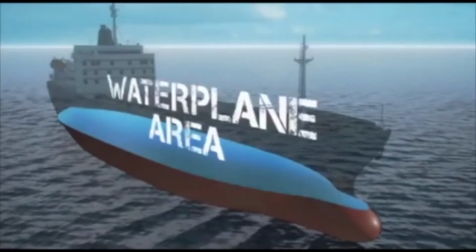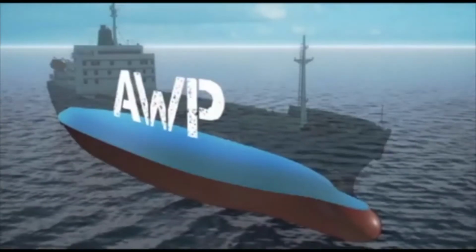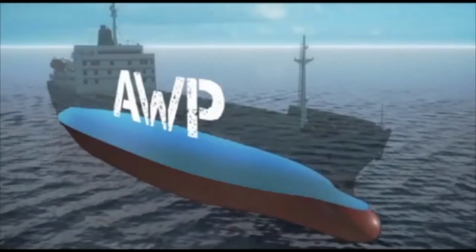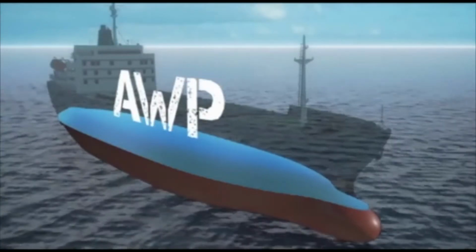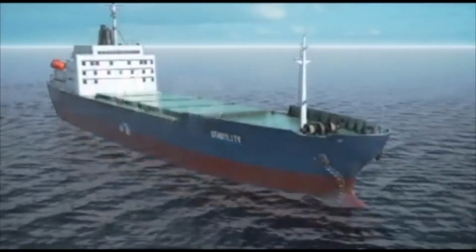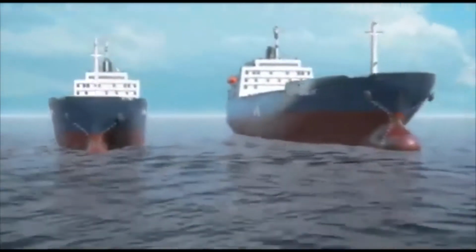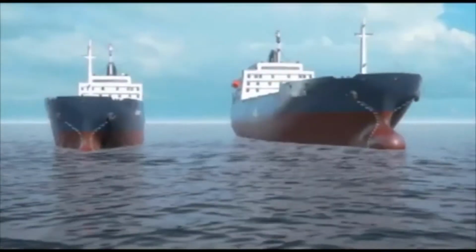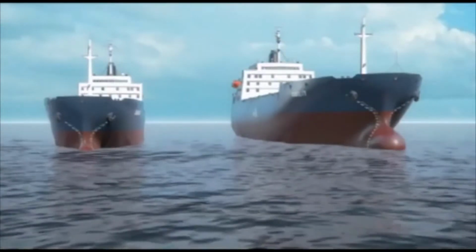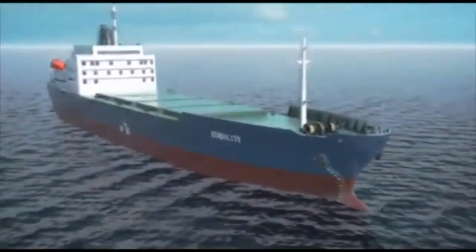The waterplane area, or AWP, of a vessel is the horizontal intersection of the waterplane and the vessel's sides. The bigger a vessel's waterplane area is, the greater the surface of the hull is that buoyancy will be acting against. For this reason, in the case of two vessels with the same weight added, the one with the greater waterplane area will have a smaller change in draft.